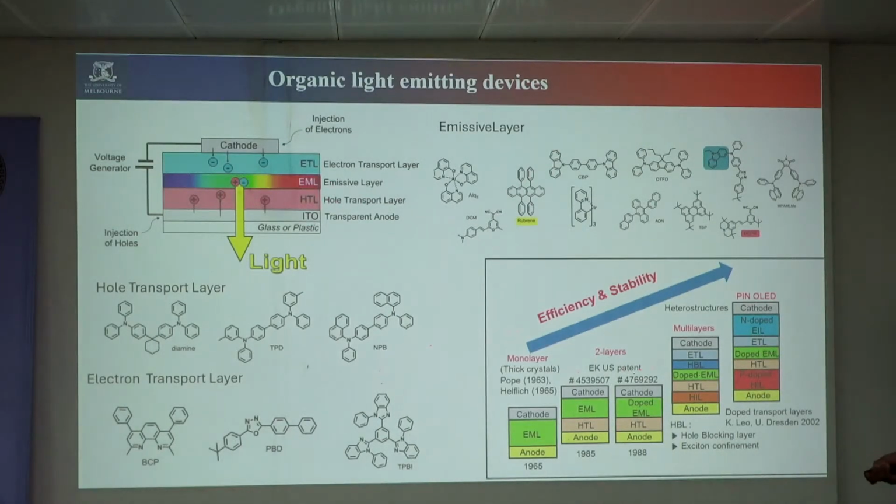And if you see the evolution of this LED, initially people tried with only the EML, with just the two electrodes. When you start with only the active layer and electrodes, they have very feeble emission. Then they found it improved a little with only the hole transport layer and emissive layer. They didn't use any electron transport layer.